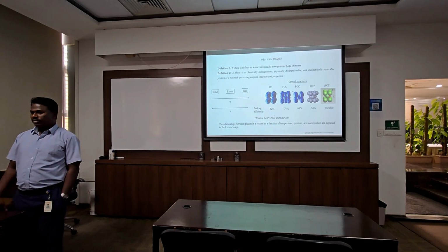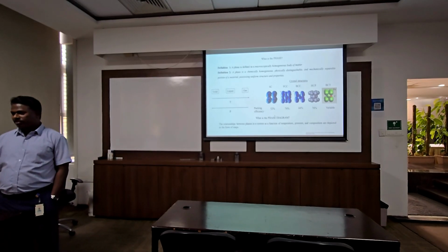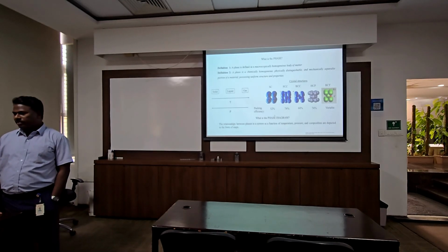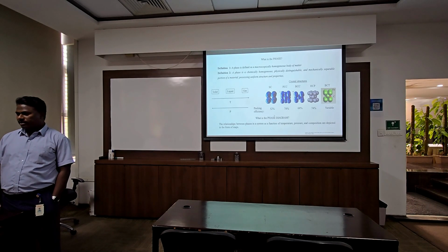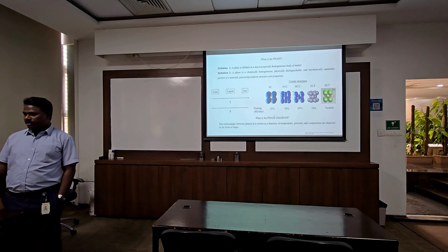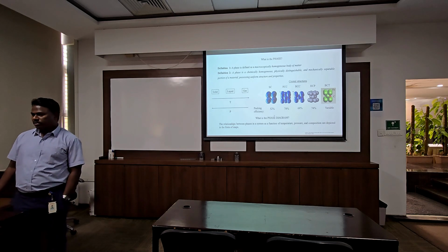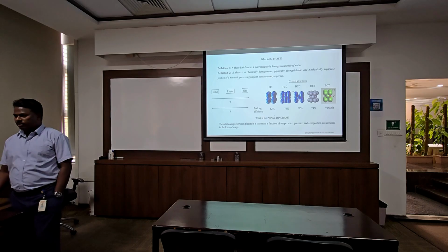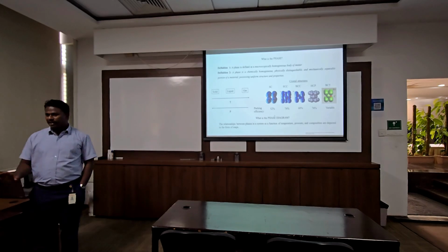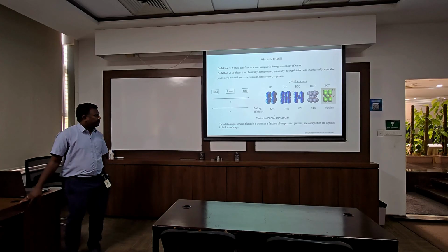So that is where we get confused actually. Basically, FCC materials are what people use at low temperature. Even in rocketry, where people store liquid nitrogen, they use austenitic stainless steel. Austenitic means FCC. So FCC is very stable at low temperature. You can even use it at minus 200 degrees centigrade. So that depends on the crystallography. That will explain it.